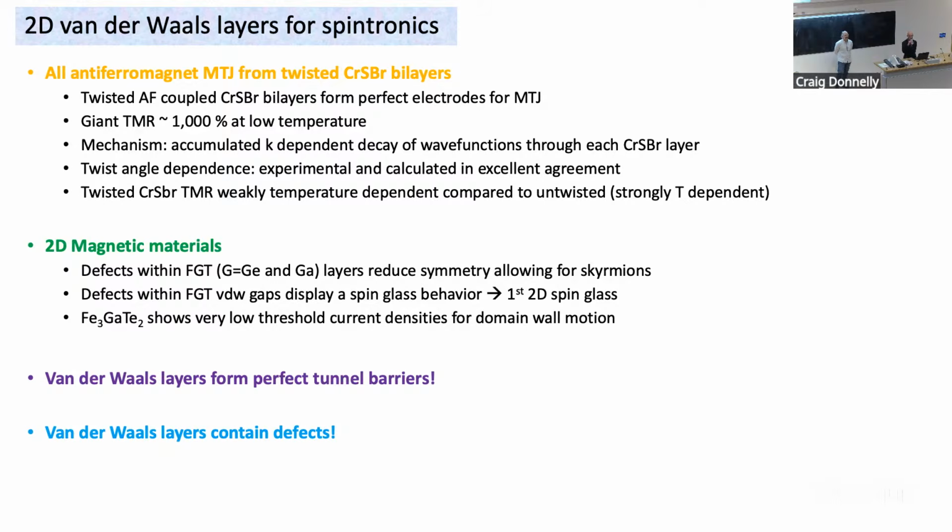Twisted layers. If you make a device with twisted layers, I can see how you can do it with individual flakes and do the twisting, but how do you do that if you're going to make that would be easy. We would just grow, let's say on two wafers, two monolayers, and then we can mechanically rotate, and this is a technique that's certainly possible. This is like wafer scale bonding.